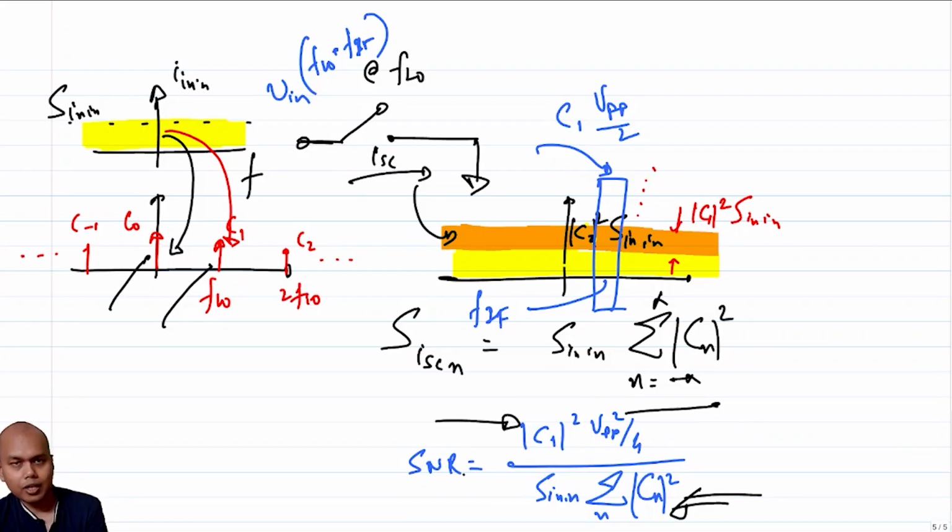You cannot really do it like an LTI transfer function, and assume that you found the transfer function corresponding to the signal, and that will also be the transfer function corresponding to the noise, because there is a harmonic folding from all multiples of your switching frequency back to wherever you are observing your signal.